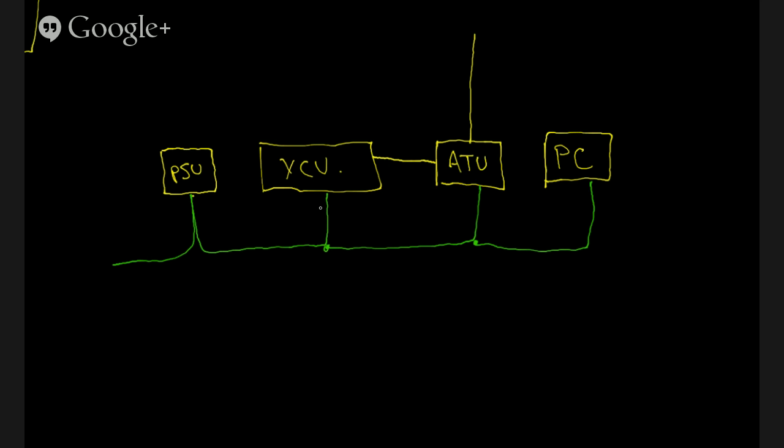These are a few schematic symbols. Earth ground is always this. This is also a grounding symbol. Specifically, it means chassis ground. And for digital circuits and analog circuitry, this will be a signal ground, which will generally be isolated from the chassis or earth ground in order to prevent ground loops.